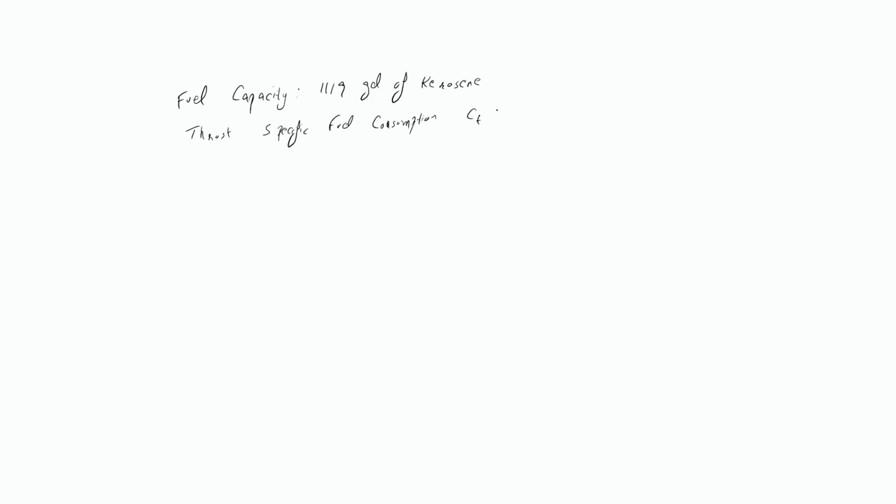Since it's a jet engine, I am denoting it by CT equals to 1.667 times 10 to the power of minus 4 per second. How are we getting these units per second? This we will be discussing in due course of time. Now the question is: plot the thrust required curve with velocity.